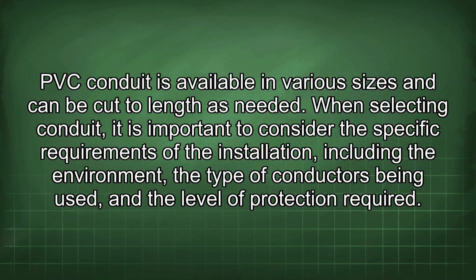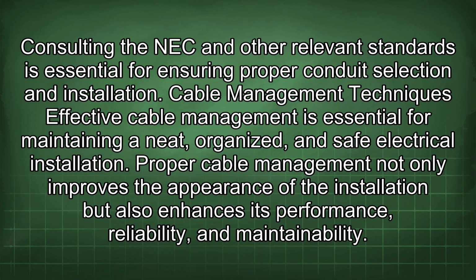When selecting conduit, it is important to consider the specific requirements of the installation, including the environment, the type of conductors being used, and the level of protection required. Consulting the NEC and other relevant standards is essential for ensuring proper conduit selection and installation.